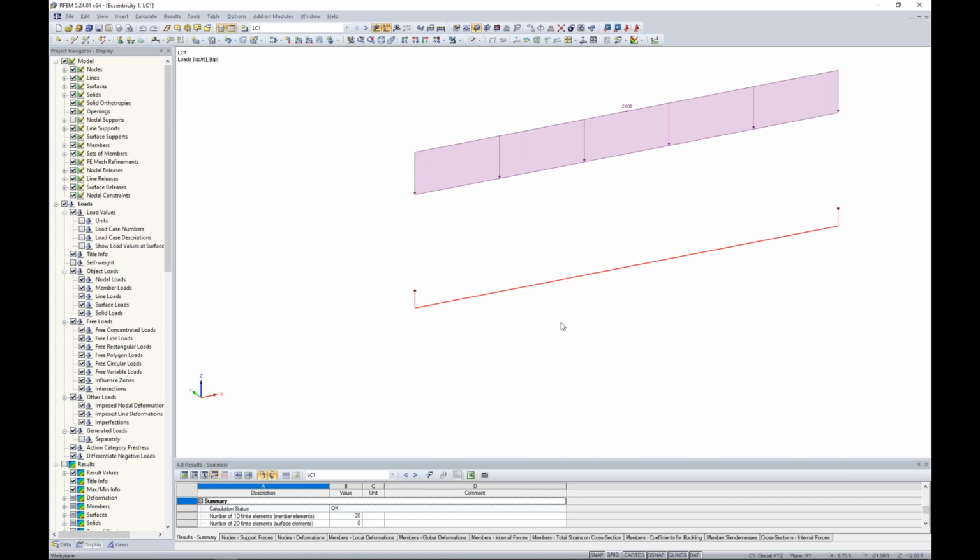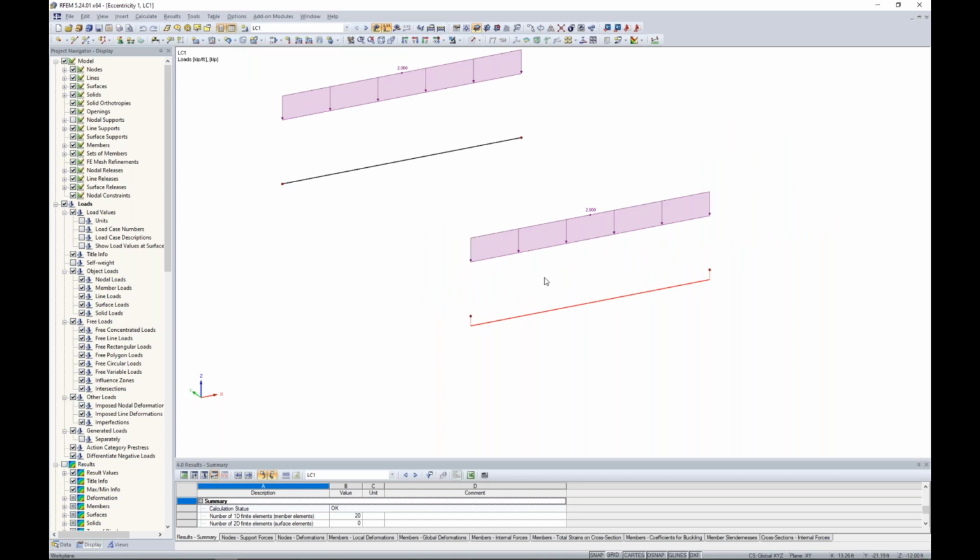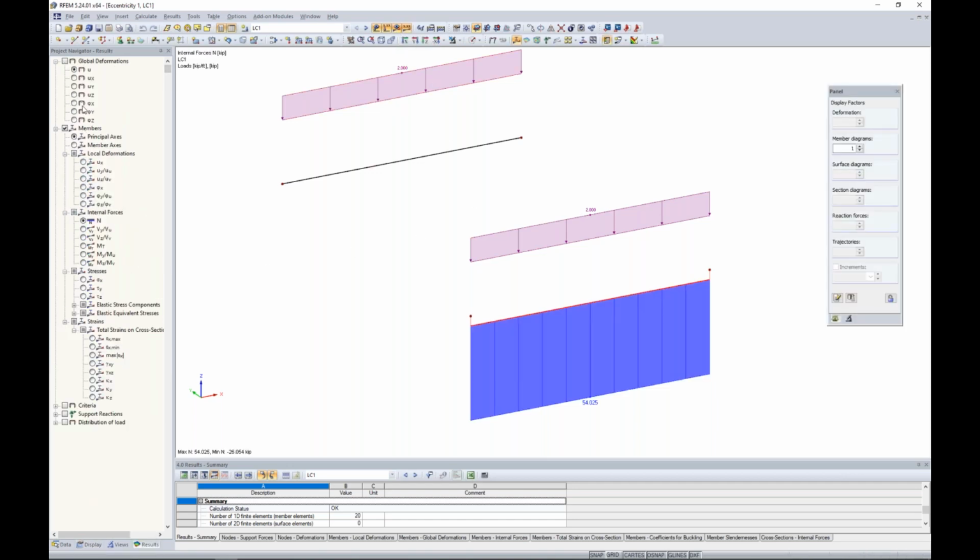Now, we're not truly adding in rigid links along the member length. It's actually taken into account with the stiffness matrix, but just an easy way to think of it is to imagine these rigid elements dropping this member down all along the length. So we might think that that's harmless, and we go to run our analysis here, both with the same distributed loads. And I'd like to take a look at the results.